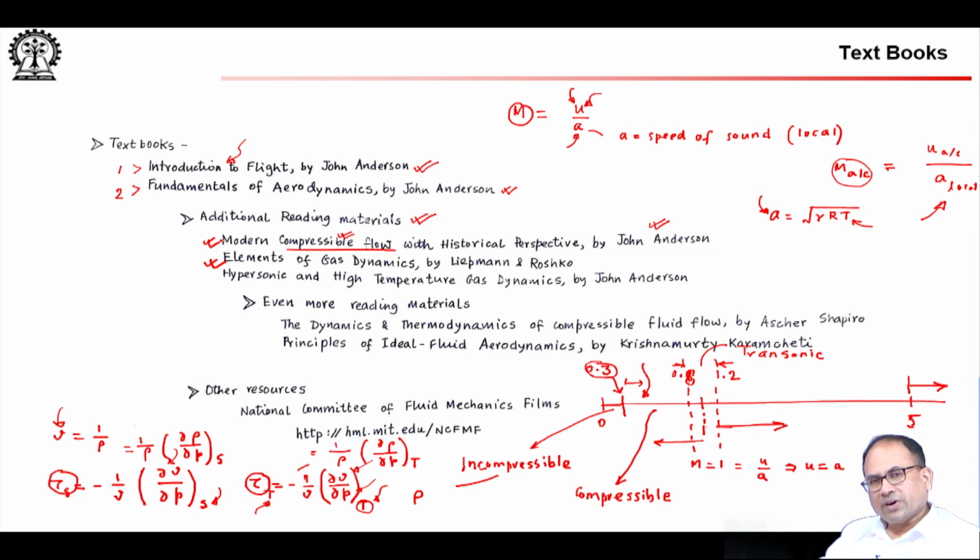Then how do we define the rotation of a fluid element, because see in a solid body, when a solid body rotates, any pair of mutually perpendicular lines, both of them rotate by the same angle. In case of a package of fluid, when it rotates, it can also deform. So, then a pair of lines that was perpendicular to each other before the rotation, after the rotation may not be perpendicular to each other. So, if you try to define rotation of a fluid element in the same way you are defining rotation for a solid element, it will not be a very apple to apple comparison.